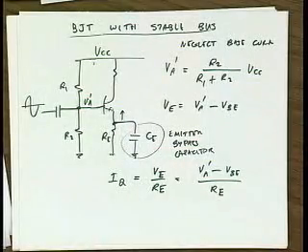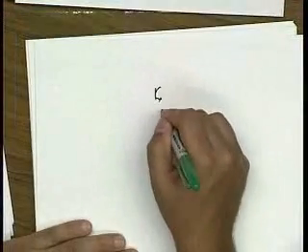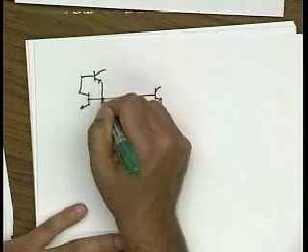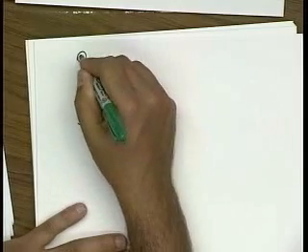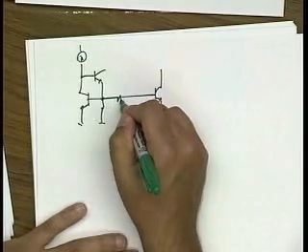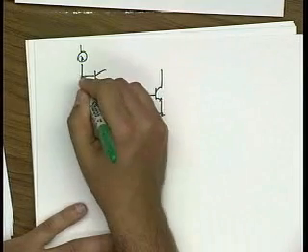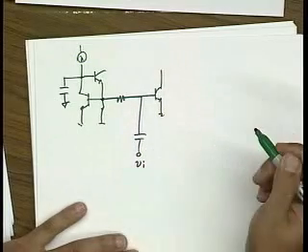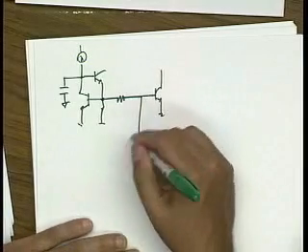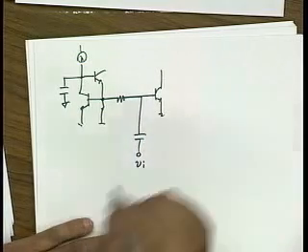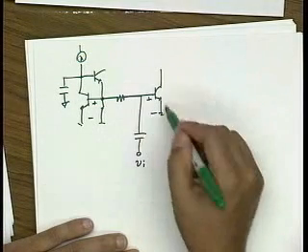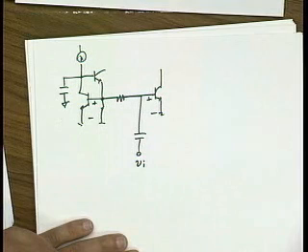Okay. Now this is the old days using discrete transistors. Nowadays, the way we would bias this up would be through a current mirror, right? So let's say this is a current mirror. This is our device. I might use a resistor to isolate this device and use a capacitor here to compensate this feedback loop and bring in my signal here. As I increase the magnitude of this signal, the average voltage here has to equal the average voltage here, and that would tend to stabilize the bias. Okay.